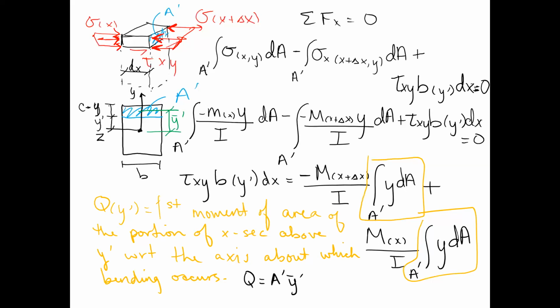Yes and no. You're asking about a value of Y that we use when we are calculating I for the cross-section. No, it's slightly different. In that case, we were looking at breaking the shape up into different areas. This is looking at a particular elevation and wanting to know what the shear stress is there. So if you're wanting to know what the shear stress is at the base of, say, the top part of a T section, then yes, it happens to be the same at that one location. But generally speaking, they're two different terms.